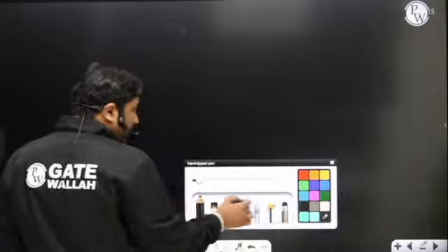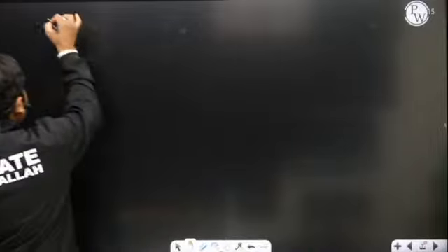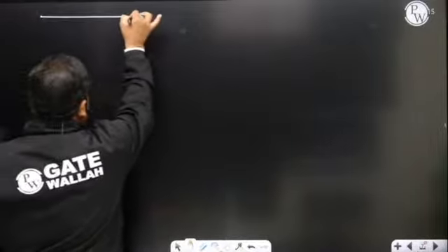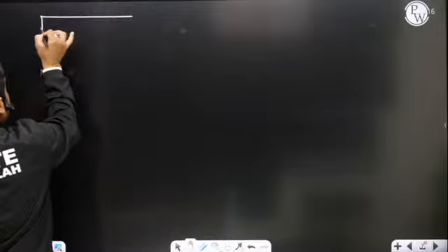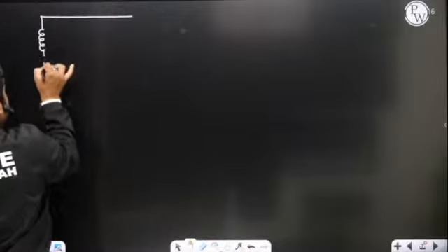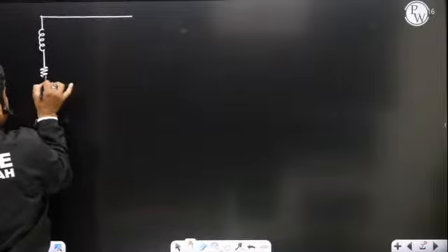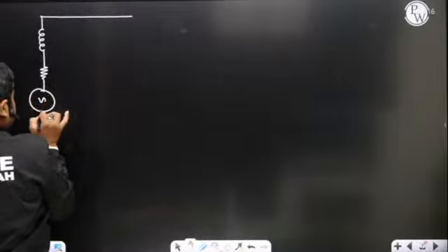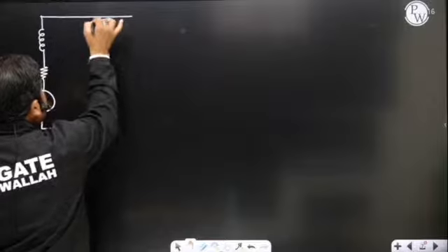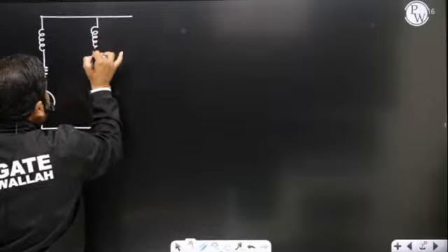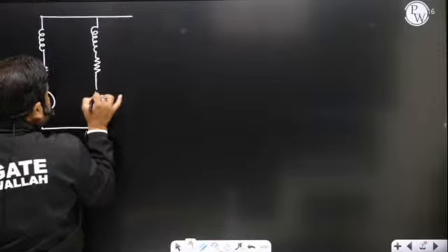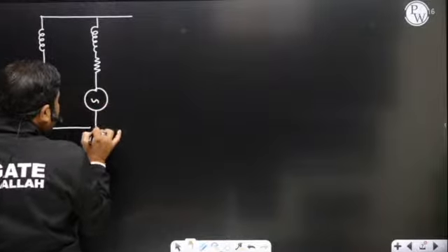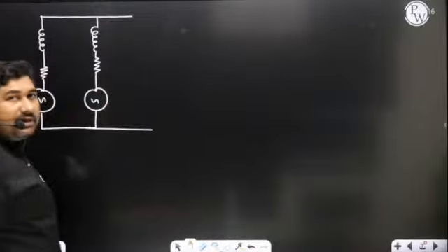Please observe here, we have two different transformers. I'm representing here a parallel combination of the transformers. The induced EMF of the transformer can be represented by a voltage source, and the winding resistances and reactances can be represented by an internal impedance of that voltage source.